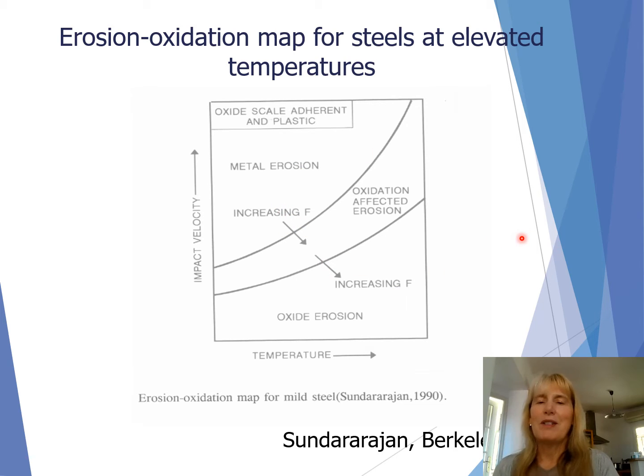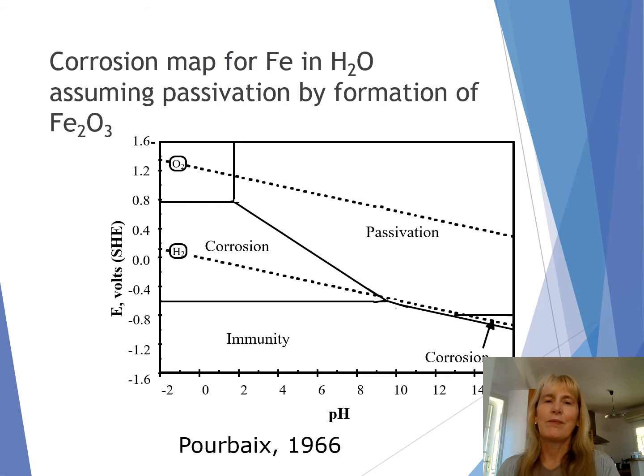The main thing about this map by comparison to the wear map is it's a slightly simpler presentation, because the extent of frictional heating in an erosion oxidation scenario is much less than in a sliding wear scenario, obviously, because you have the integral surface sliding against the counterface. So that's the difference really in the boundaries.